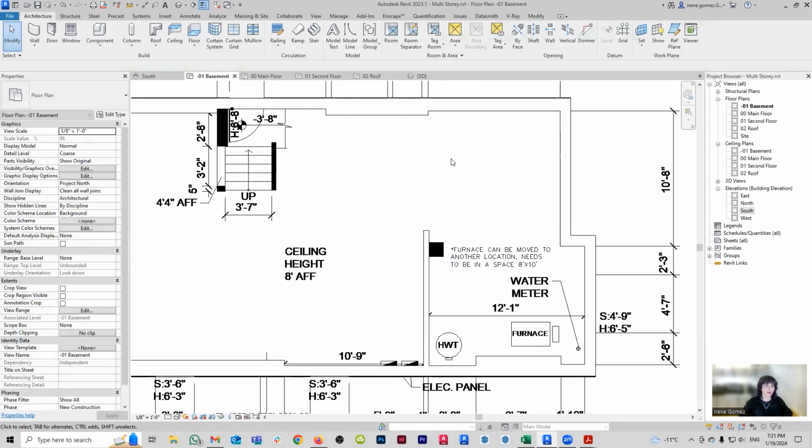Now, one thing that you need to be careful about when you start adding walls after you've set up your floor: because we have made it so our walls go to the main level, you need to make sure that they are not going through your ceiling. So we might need to do some adjustments. We might need to add a little bit of an offset.